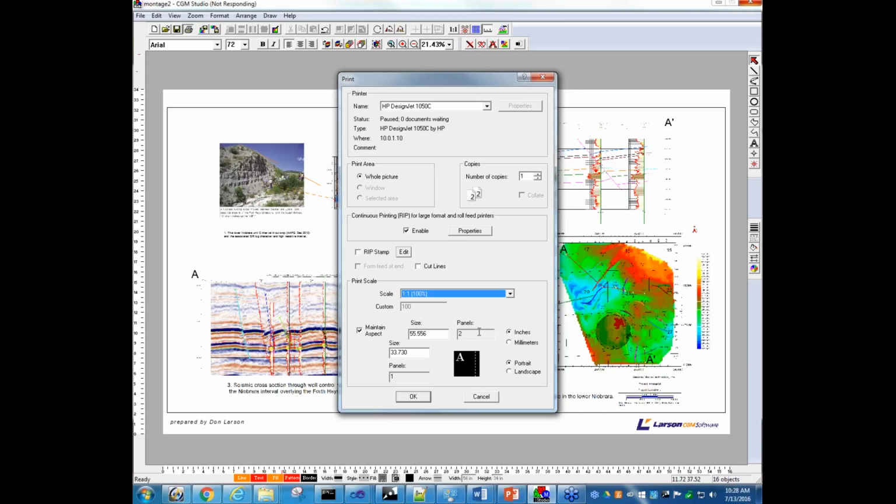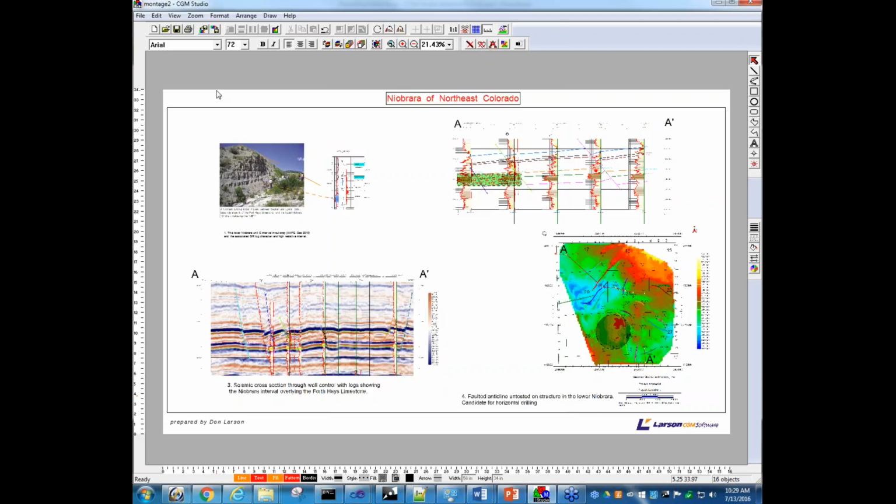Well, I know that this plotter is a 34-inch plotter, and my presentation is too big to fit on that, so it shows you that it's going to want to panel it. This little icon here shows it's going to try to panel it. Well, we don't want to do that probably. Let's go into landscape mode. It's going to flip it now, and you notice 1:1 panel, so that means it'll all fit on your paper without having to break it up into strips. So let's just cancel out of there because I don't necessarily want to print right now.